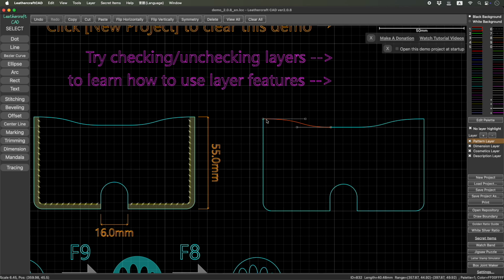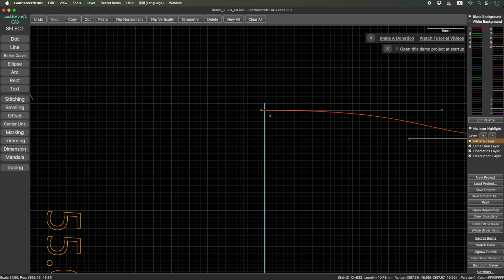And if the shape is not closed, like this one, which is obviously not closed, you will not be able to convert this into a colored template. What happens if you do that? Let me do it quickly, and press F9, and it does convert the shapes into a single template object, but it will not be colored. So let me undo, and then connect. And also if you see a red dot, this one looks closed, but when you magnify it, you see a red dot here.